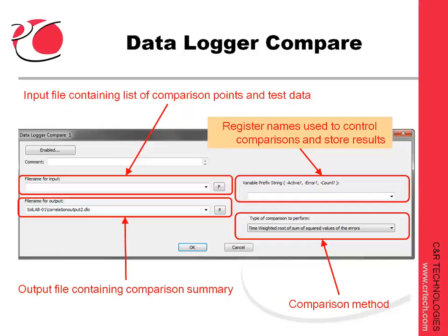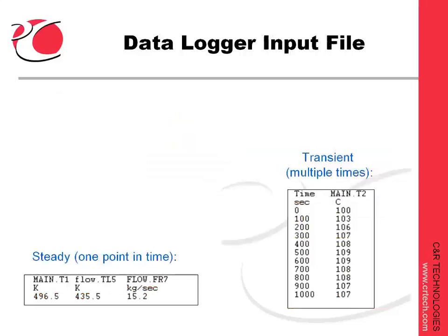These are optional advanced features used in logic. For example, they allow you to turn the logger on and off within a run. That would be useful if you want to run a setup case like a steady state before starting the actual solver procedure, and you don't want the logger to start its comparison tally too soon. I won't be covering these features in this overview, but you can read about them in the TD manual.